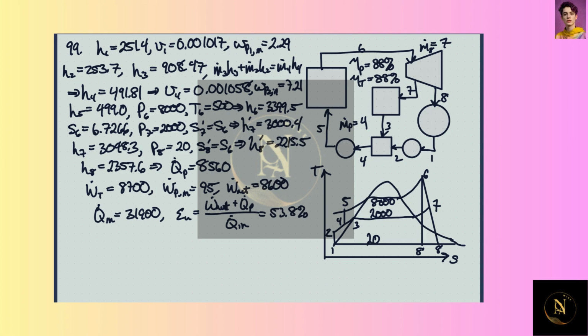So that gives us, we know everything in here except for H4, so we can find the enthalpy, specific enthalpy that is, coming out of H4, which then allows us to figure out what the specific volume at 4 is, because we also know the pressure. And with that specific volume and the pressure change between 4 and 5, we can get the specific work that this pump here does on the steam, or the liquid, the water at this point.